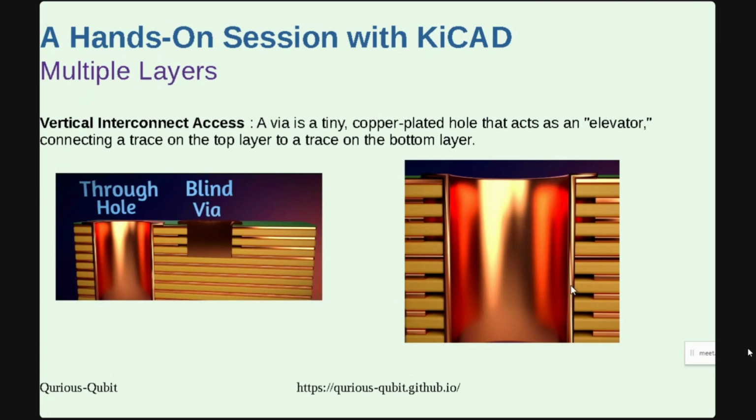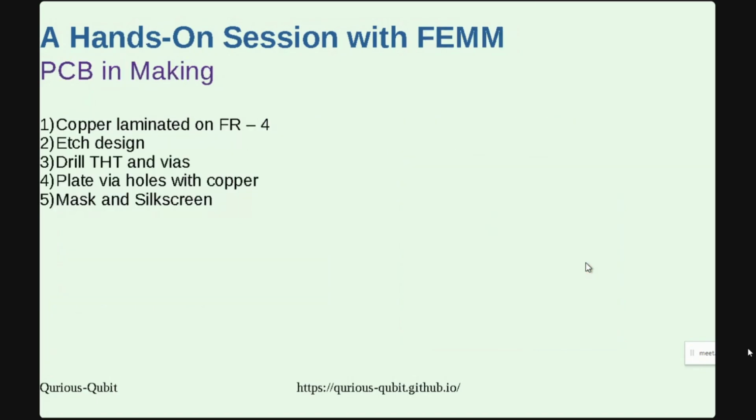They are not connected to this particular hole or drill, you can say, a particular THC hole. So you can have this configuration made. This is why making PCBs is a highly technical and highly skilled thing to do. So that's how you avoid connecting to different layers. You have to plan properly and choose a layer to have your components connect. That's about PCB.